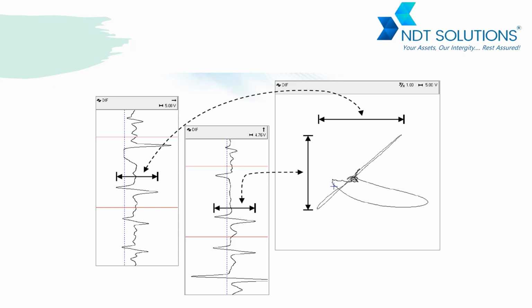So for vertical, if we click on the vertical channel, this represents this value here. We can measure it as a phase or voltage, whatever it is. This will represent the vertical value. And if you are clicking on the horizontal one, this horizontal one is this one. The voltage will show here, how much voltage it represents, like this one.